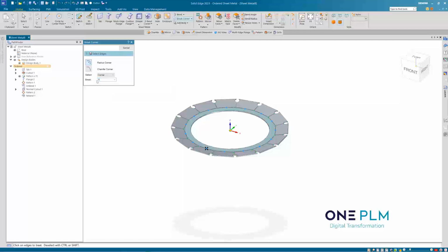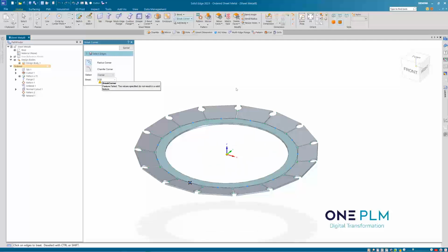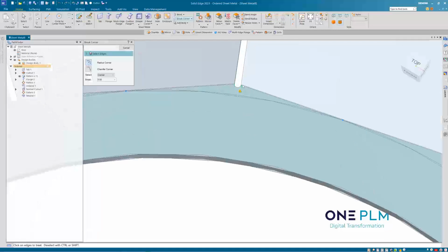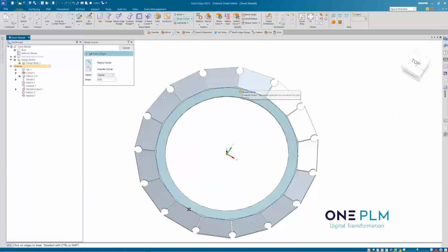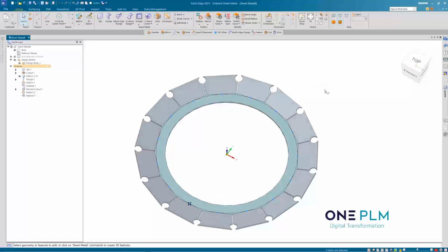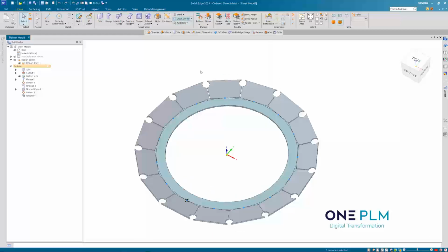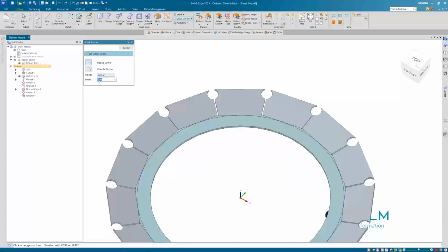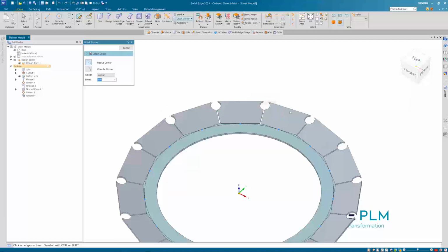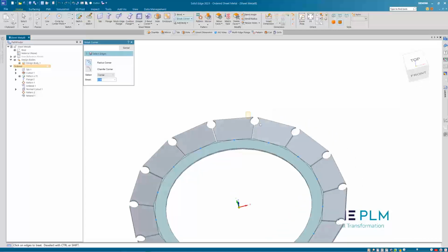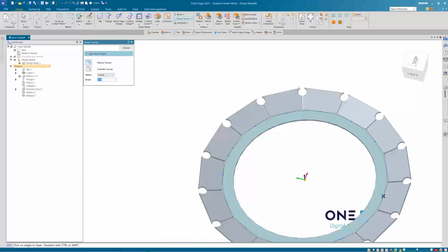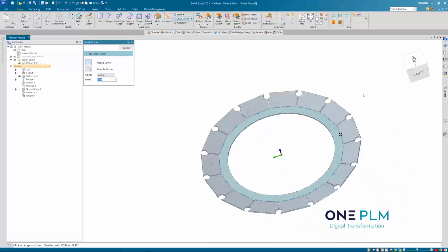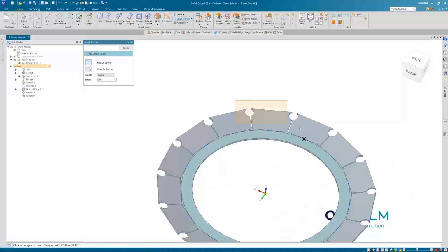If it won't do it, just try some different sizes. So go and change those up and down because it's kind of picking up these corners, which is actually what the problem is on there. So that's where it might be easier if I just do the break corner. I go and kind of fence select there, say 1 mil. So 0.5 will be fine on that. And then it's just a matter of just going around and selecting those, or we could go and do a pattern on those if we wanted to, but sometimes just doing it manually can be fun.